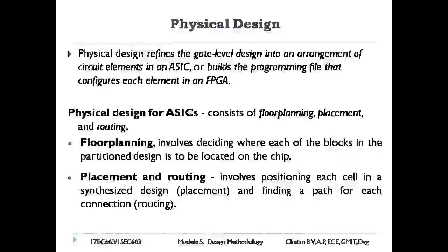Floor planning. Floor planning involves deciding where each of the blocks in the partitioned design is to be located on the chip. A number of factors influence the floor plan. The first one is that blocks that have a large number of connections between them should be placed near each other. Second, blocks that are connected to external pins should be placed near the edge of the chip.